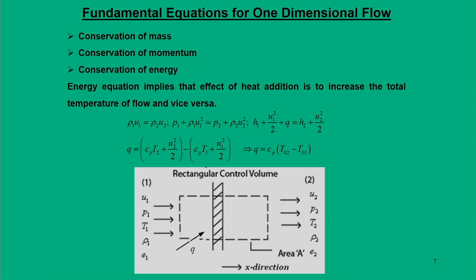So, the next aspect we are going to study is that with this control volume of a one dimensional medium, we are going to write the fundamental equations. Those equations are conservation of mass, and the first equation written here is rho 1 u 1 is equal to rho 2 u 2. So, it is the mass conservation.